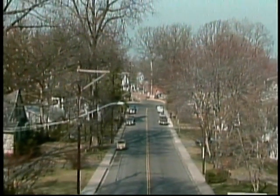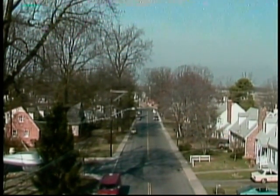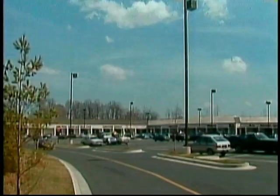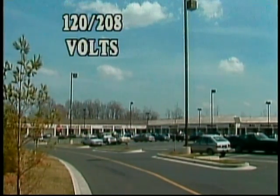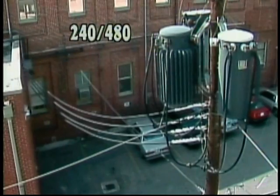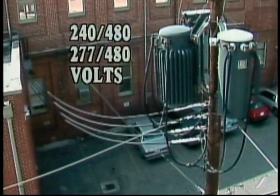Secondary system voltage, sometimes called utilization voltage, can also vary. For example, a 120-240 volt single-phase secondary system is common for residential customers. A 120-208 volt three-phase secondary system may be used for light commercial customers, such as small shopping malls. And a 240-480 or 277-480 volt three-phase secondary system may be used for heavier commercial and industrial customers.